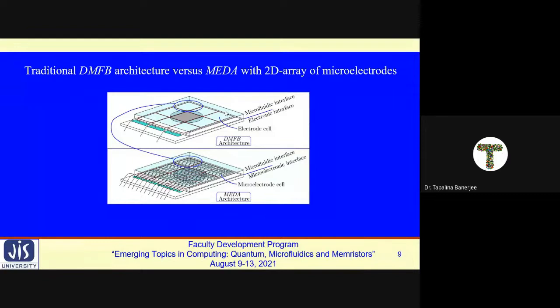So due to architectural flexibility, MEDA biochips can perform some advanced microfluidic operations such as channel dispensing, fluid merging operation, etc., which are not possible in traditional DMFBs without errors. So MEDA can precisely dispense a certain amount of fluid using channel dispensing operations.